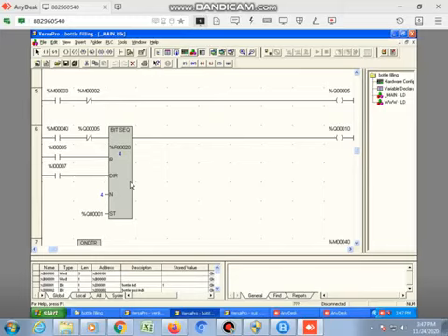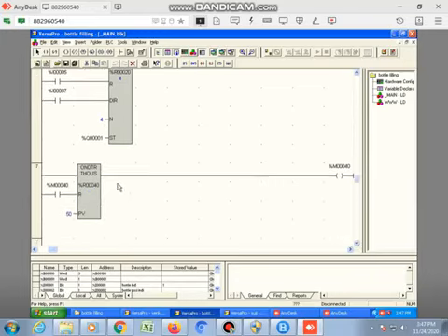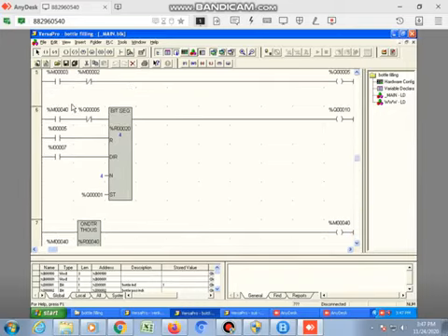On what sequence we have to give the supply to these 4 coils can be given by another timer. This is giving a change in the output sequence every 5 milliseconds. So at the 0th second we get the first coil, at the 5th millisecond the second coil, at the 10th millisecond the next, and like that we get a continuous change. This memory 40 is connected to the bit sequencer. This is the output for stepper motor control.